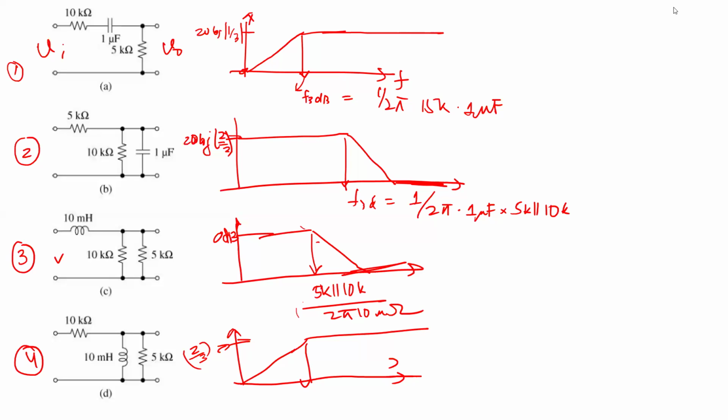When you're doing board design, you can use inductors to do low pass design, because you can have big inductors, in microhenries. In IC design, even the bond wire, the big wire which goes from the die and joins the lead pad, is only in nanohenries. Anything inside the chip is in picohenries or attohenries, so they're almost negligible.